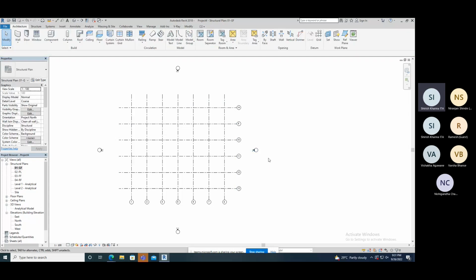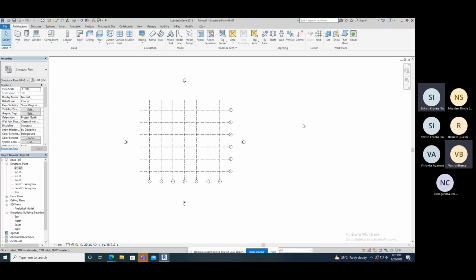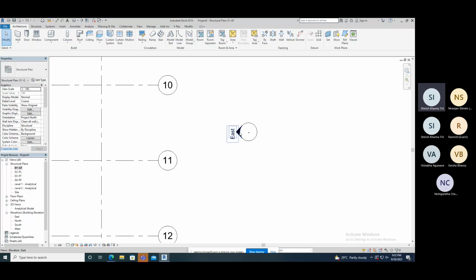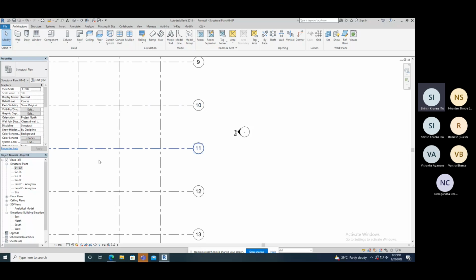Okay. You can move your elevations. See, if you are creating outside, that is not visible. Suppose I'm creating here. It is not visible in east elevation because east elevation shows only its left side, not right side. If you want to see both sides, just click on it.